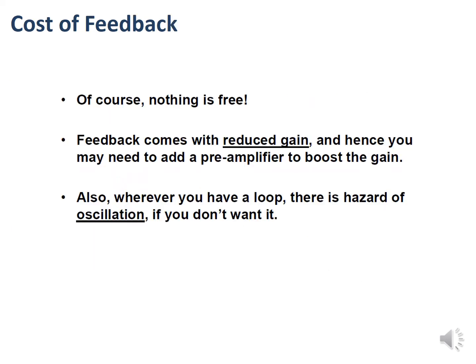So we've seen that feedback can be a very positive thing. It enables us to predict very accurately what the gain of the circuit is. It reduces noise, and we've seen some of the other advantages. But of course, nothing is free, and the downside of feedback is that it reduces the gain. The amplifier circuit, in our case maybe an op-amp or a transistor amplifier of some kind, may have a very high inherent gain. We're going to reduce that with the feedback, but the circuit is going to become a lot more stable, and I've got the benefits we've already looked at.